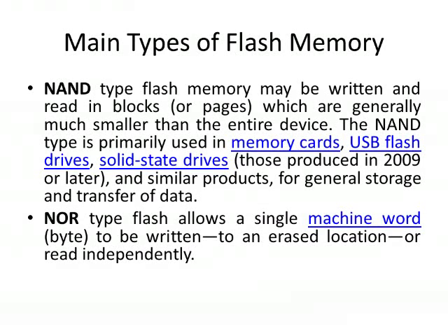NAND, however, has a significantly higher storage capacity than NOR. It has found a market in devices to which large files are frequently uploaded and replaced. MP3 players, digital cameras, and USB drives use NAND flash. NAND devices are accessed serially using the same 8 pins to transmit control, addressing, and data.